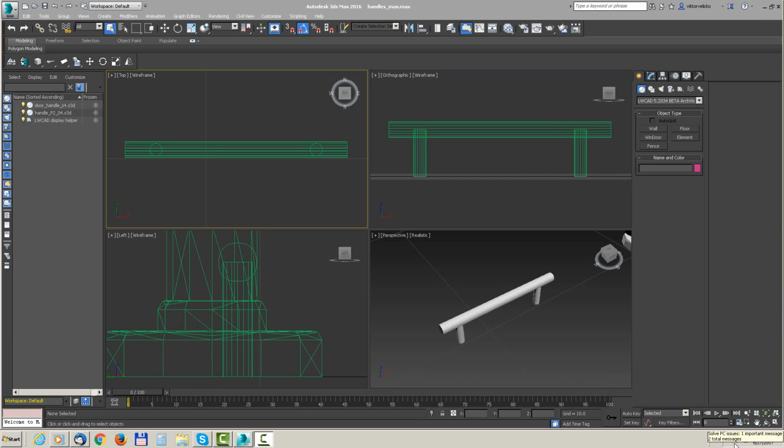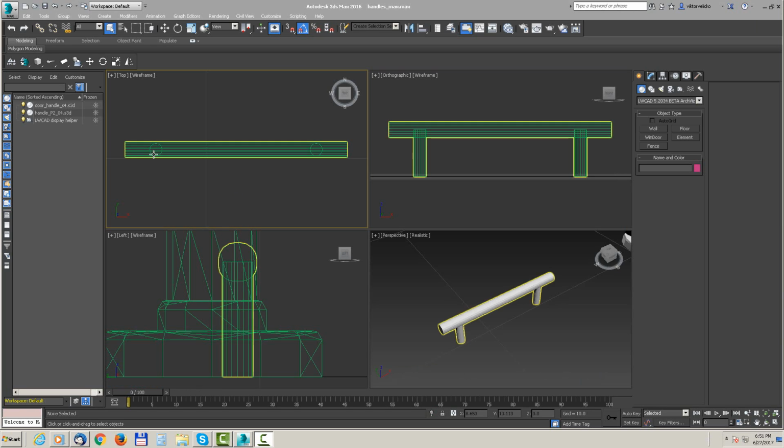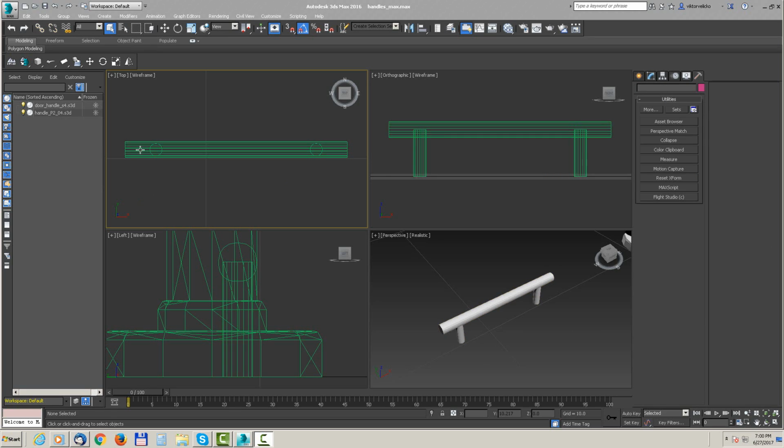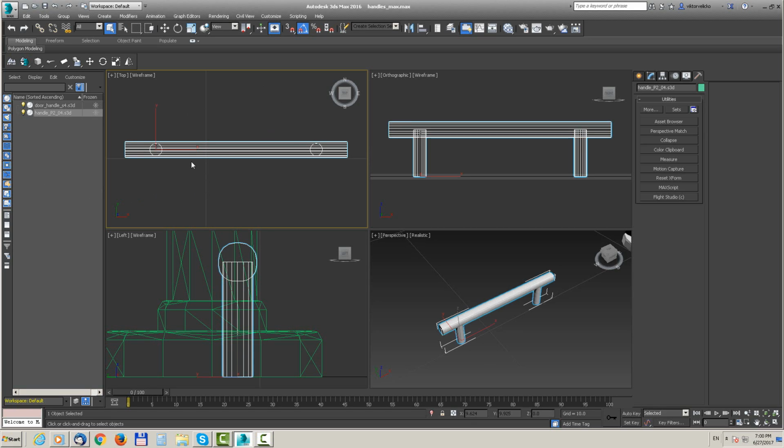Intervals. In element objects, we are setting intervals only in case we have both pivots, because with both pivots the object is stretching and we can set intervals. Otherwise it doesn't make sense to set them. We add this object into the element library again, but now with defined intervals.